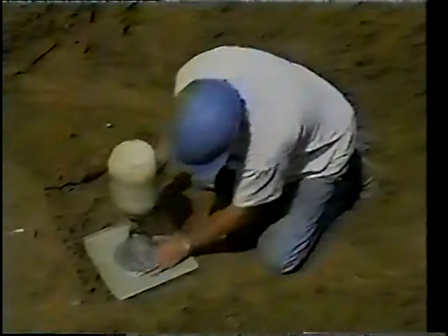Embedment soil should be spread equally on both sides of the pipe and compacted to be dense and stable. The difficult part is here, in the haunch area. The soil needs to be placed and compacted with particular care if it is to support the pipe properly. The degree of compaction can be measured with an in situ density test suitable for the soil type, and the result compared to a laboratory maximum density.